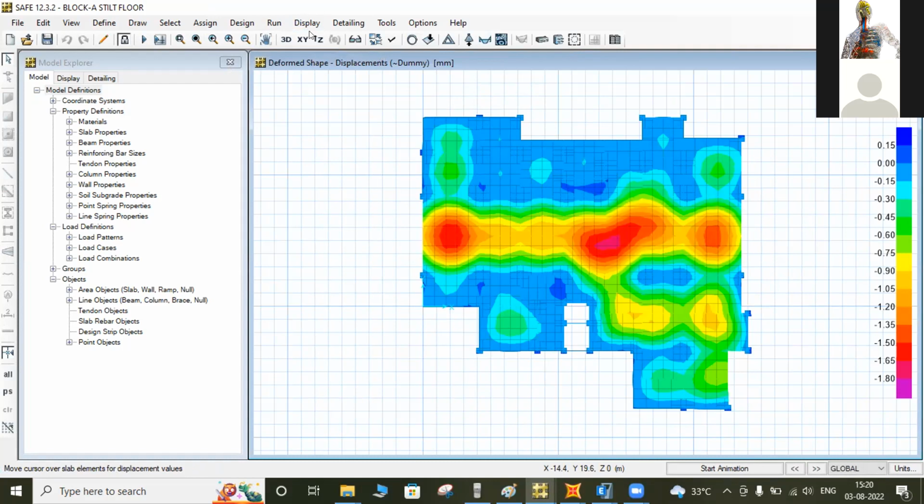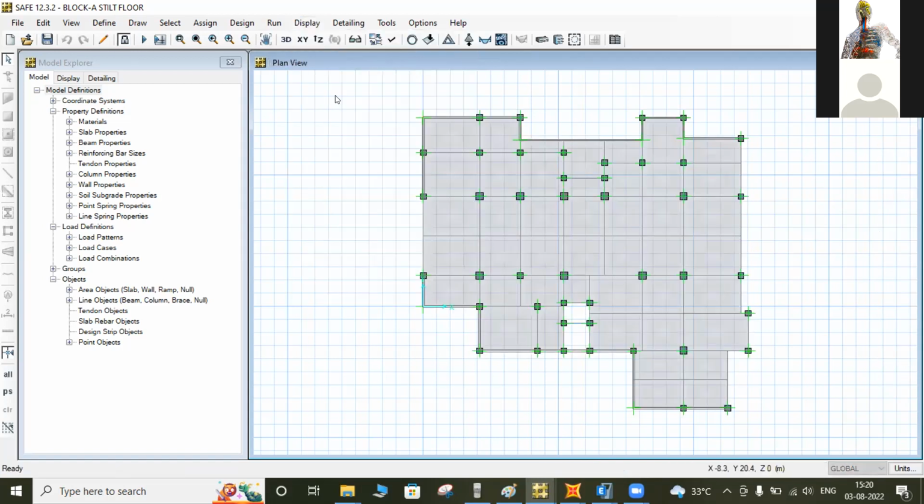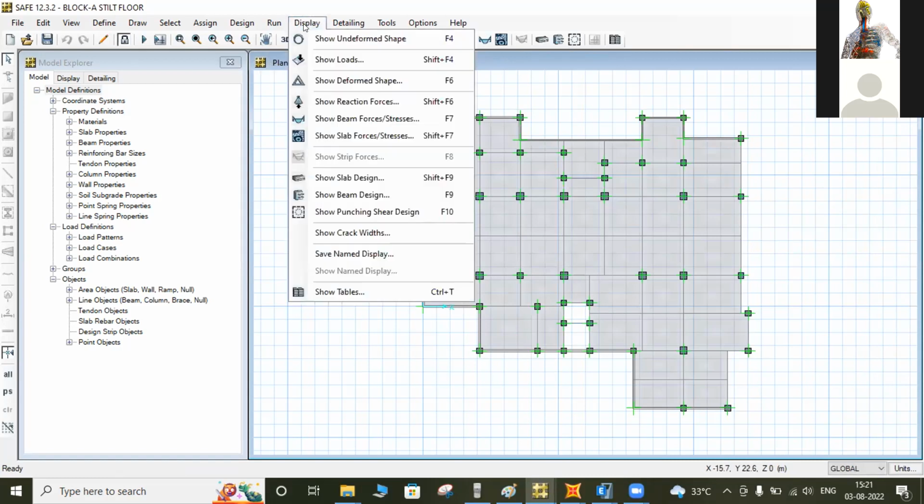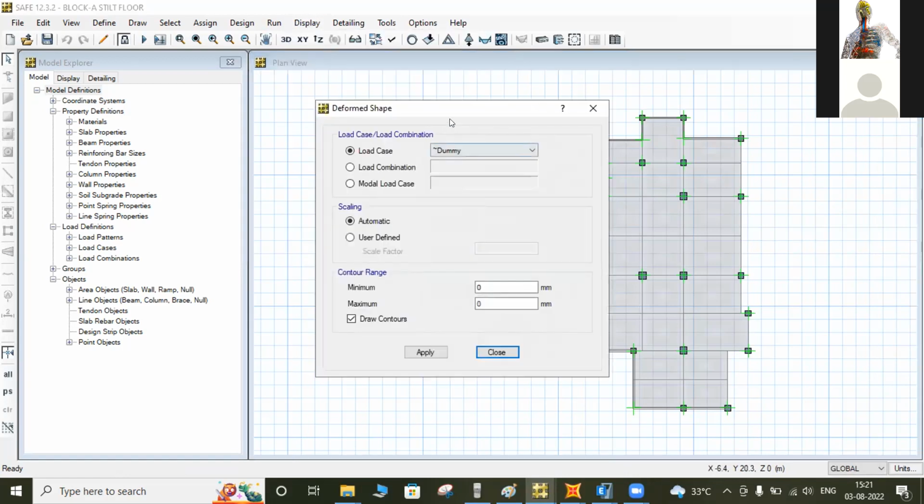Similarly, we can identify the reinforcement, like the foundation part, the raft, that we discussed previously. The same checks apply, but in this part we have no need for the punching value. You have to consider the flat slabs, the deflection check, and other checks, so that your results become sufficient. You can design the slab as per the previous foundation raft, following the same steps.